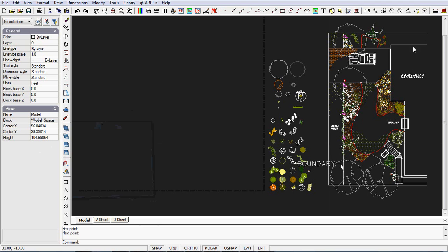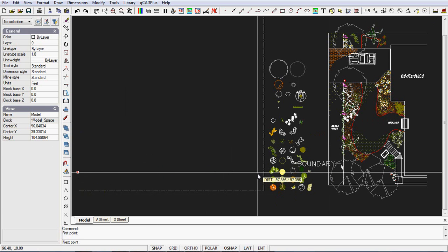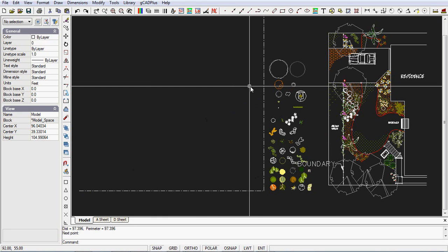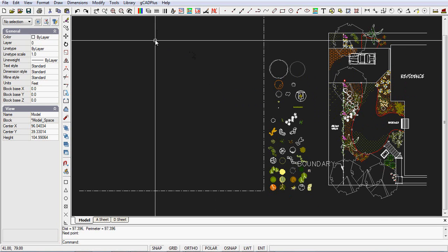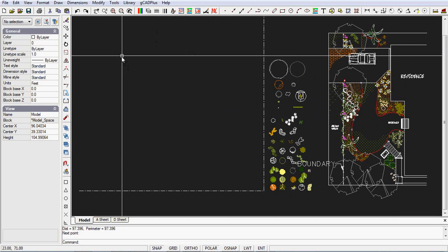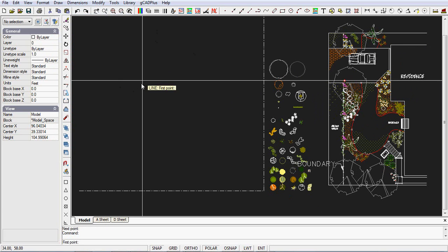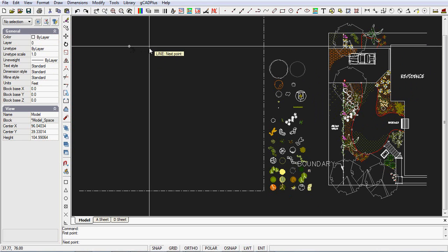We'll start by simply taking that measure tool and just checking that from here across to about here we've got enough space, and we do have 97 metres, so the whole design will fit in the space that we've got. What we'll do now is start up in this corner of the house and start working with our mud map. So let's begin. We'll start by going Draw and Line, and for the moment we'll just pick an arbitrary point somewhere around top left and head off in the direction we want to go.